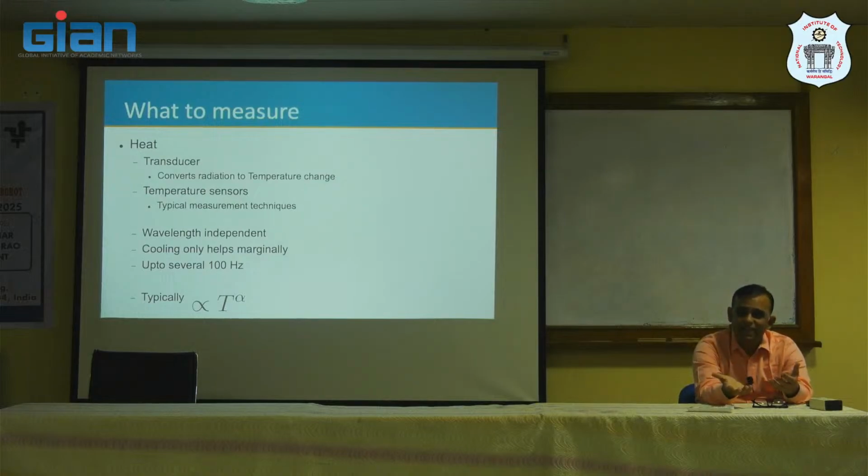If our sensor itself is producing 100 electrons as part of thermal noise, I will not be able to read these 100 photons. So, 100 photons will produce 100 electrons. My sensor noise is, say, not even 100, it is 50. Then my signal to noise ratio is quite low. So, quite often in these extreme applications, we cool the camera to very low temperatures, sometimes at 4K, sometimes at around 70 or 80K. And at that temperature, the thermally generated charge carriers will be low, which means whatever we will be measuring will be intensity effects.